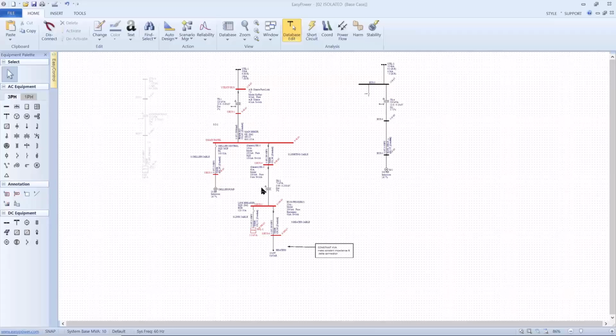Before diving into large projects, what are the sequence of checks we need to perform? Homer, that's essentially what I walked through. Make sure you can do a short circuit analysis and get results on each bus. Make sure you can do equipment duty results. And then make sure you have sequence of events capability, and frankly, power flow. By going through those 4 steps, you don't have to debug it. You just have to make sure you're getting results. Then you know that your debug time will be productive or not wasted trying to fix bugs.